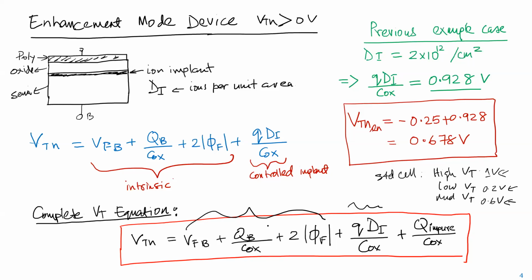But this part is already built into your device. So when you choose a technology, you just get this, and then with temperature this will vary, but you can't change the VT. It'll vary with process, what's called process corners, because they can't really control this very accurately. So even this quantity varies quite a bit from part to part, and then varies over temperature as well.